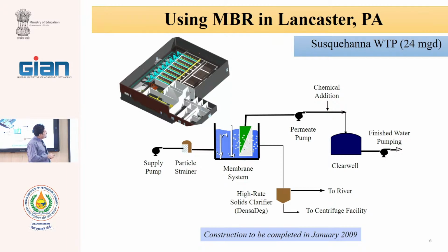Therefore, it is better that after the MBR we use advanced oxidation processes, AOPs, in which, with the use of UV, H2O2, photocatalyst, Fenton, electro-Fenton, and other radical production processes, we can remove all our pollutants completely. In new systems, after MBR, usually AOP processes are used for complete removal.